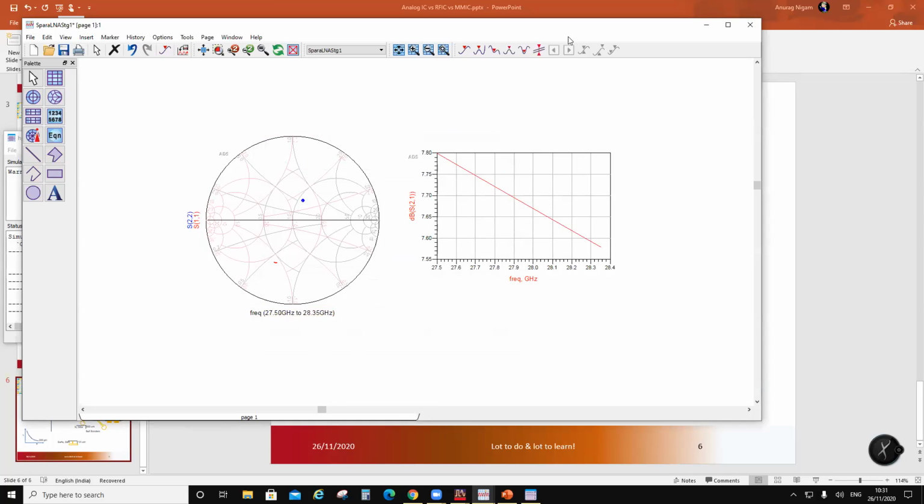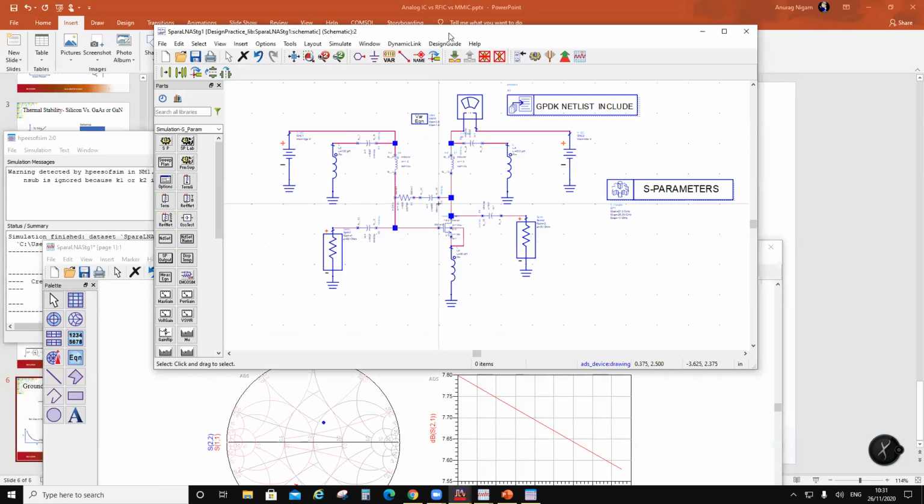One more thing I want to tell you is the following. These inductors, if they are not large enough, they are part of the tuning. When they become part of the tuning, then this ground has to be very good. Otherwise the internal impedance of the supplies is going to start affecting you. It will not affect you in CW.